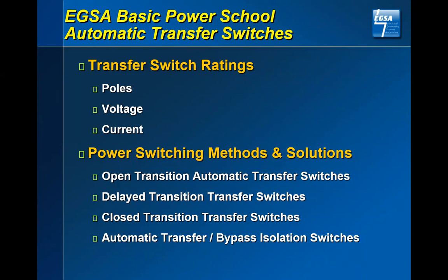Several manufacturers do that. The delay transition switch will open a hot source and disconnect both services before it connects to the second service. Why is that? If you have a large motor of some type, or some type of industrial process, you don't want that switch to transfer as quickly as an open transition. You would want to open the power, let the motor wind down, and then at some point, whatever that constant may be, it may be a few seconds, it may be 30 seconds or so, then you will re-energize that.